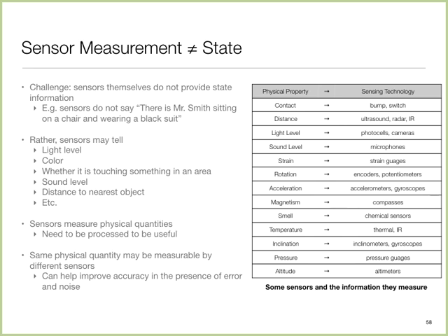To give you one example, the accelerometers which are built into our phones, and many of you are using in the projects, can pick up sound. The reason they pick up sound is that they are basically little MEMS sensors, a mechanical thing suspended in a chip, so they measure vibrations. When there are air pressure waves, they move that object around, and that's what the signal picks up. People have shown that gyros and accelerometers in your phone pick up sound to the